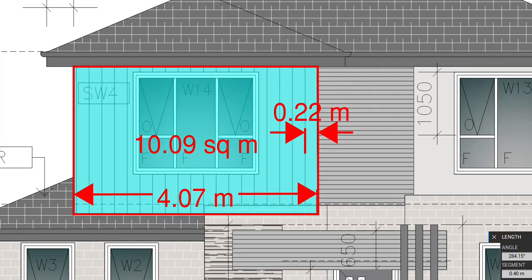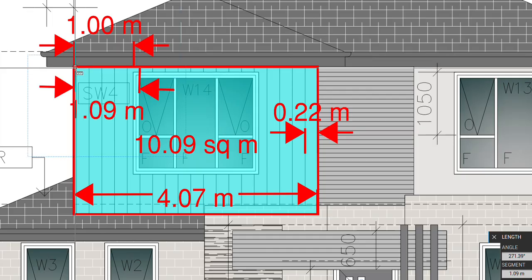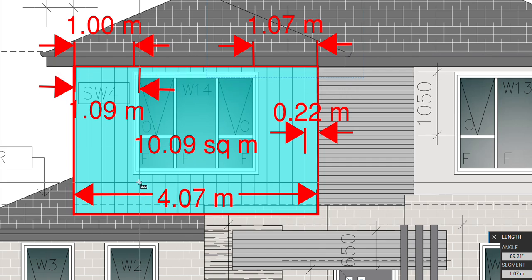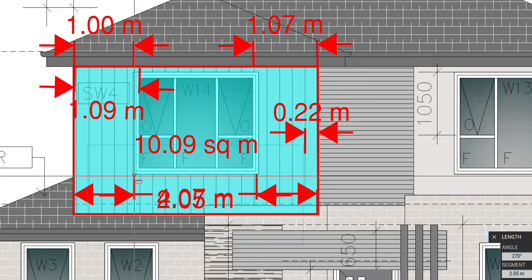What we do in this case, we will take the partial area, like from here to here, where the panel will become a full panel. If you can see, you can check. Here are the panels, and here we will take full panels. But for this remaining area, we will take the length of the upper and the lower side of the window.